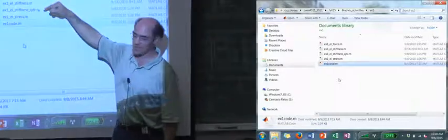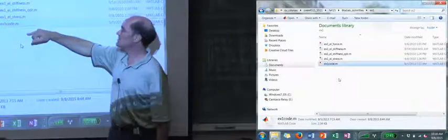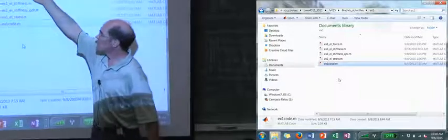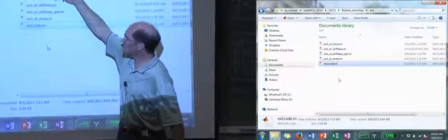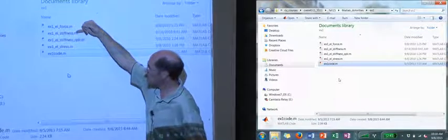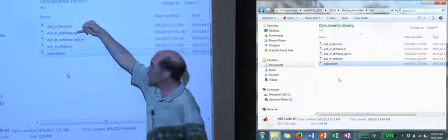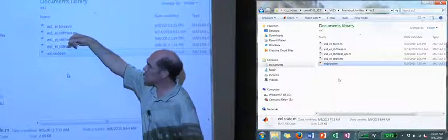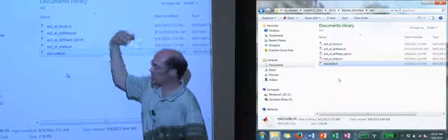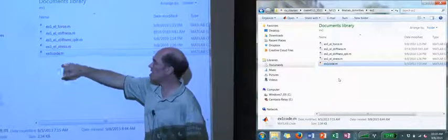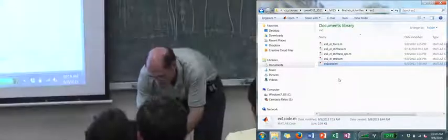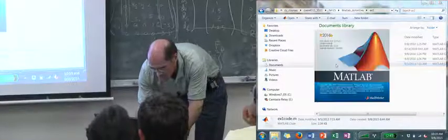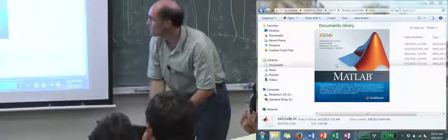This is written in MATLAB. It's not very elegant, but it gives you the general idea: there's a distributed element forcing vector subroutine, there's the stiffness matrix subroutine when E and A are constant, and then there's one where A is quadratic. Then there's the post-processing step for stress, which we haven't shown on the board yet, and then there's the driving code. We call it EX1 code. Let's open up EX1 code and see what that looks like.